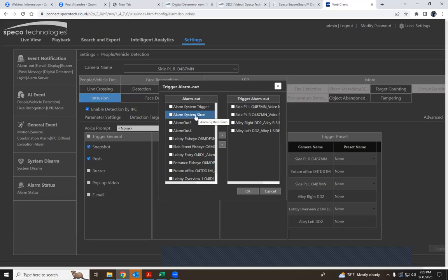So if I see something happening that I don't necessarily want the police dispatched from my alarm system, then I'm able to just trigger the sirens. For those that are thinking down the rabbit hole where I'm at, you can also put a TTL relay on any siren or strobe that you've powered up locally, and also run that into one of your alarm outputs through that TTL relay and do the same thing without utilizing an alarm system. There's multiple integrations that you can do.